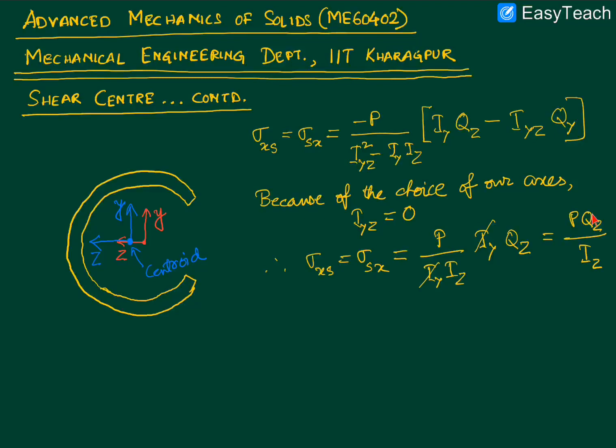But this QZ, it's like a local property. So every point where you sit here, when you sit here at different points of this member, the value of the QZ is going to be different. So it's like the first moment of area that is present over this, and this thing will be absolutely clear when we actually compute it.